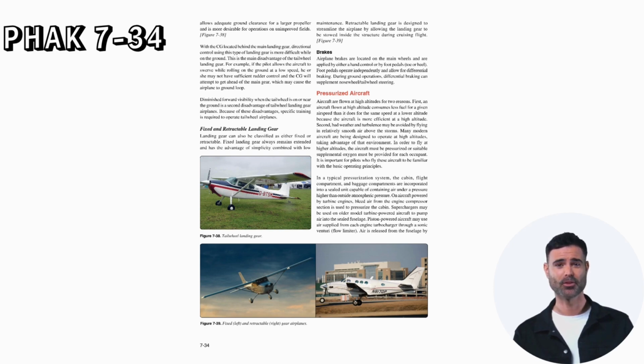Pressurized aircraft are flown at high altitudes for 2 reasons. First, an aircraft flown at high altitude consumes less fuel for a given airspeed than it does for the same speed at a lower altitude, because the aircraft is more efficient at a high altitude. Second, bad weather and turbulence may be avoided by flying in relatively smooth air above the storms. Many modern aircraft are being designed to operate at high altitudes, taking advantage of that environment.